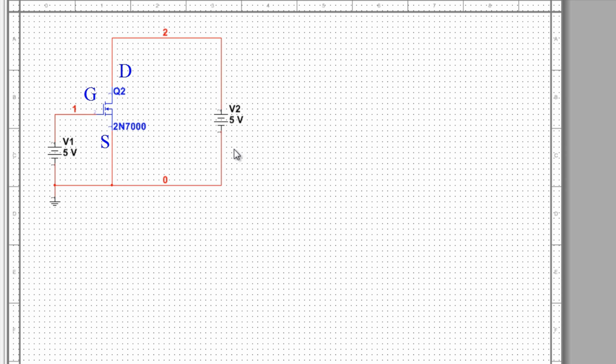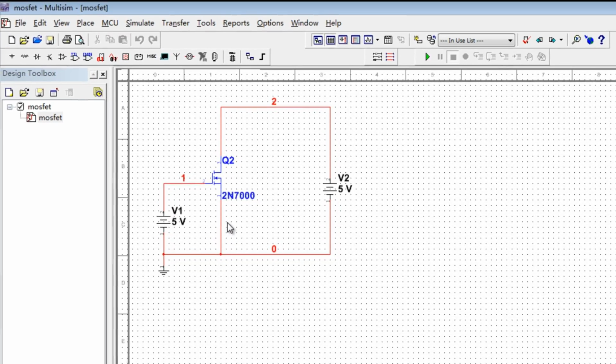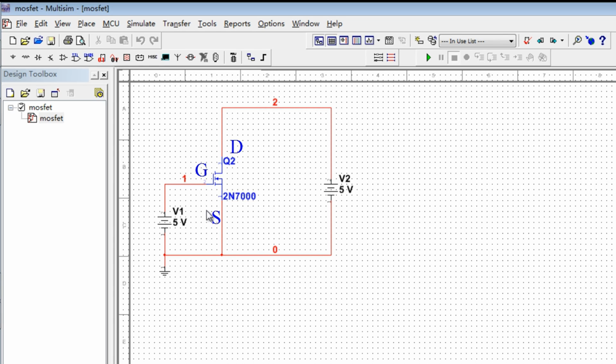It should be emphasized that this is not a standard functional circuit of the MOSFET. We use this circuit to measure the port characteristics of the MOSFET. In the second simulation instruction after this lecture, we will show you the detailed characteristics of the MOSFET. Then you will know that G is open with respect to the other parts of the circuit, so there is never any current.